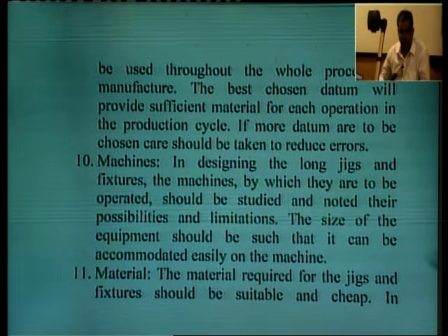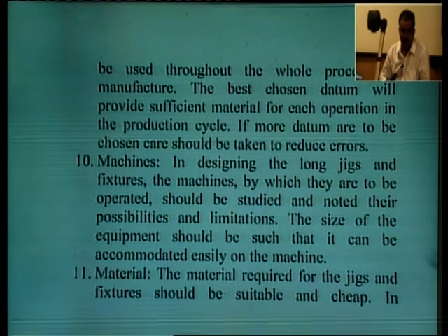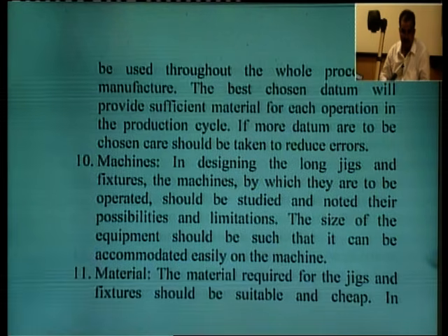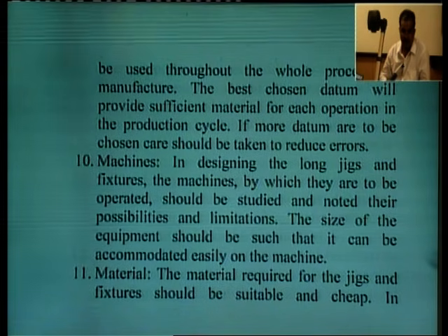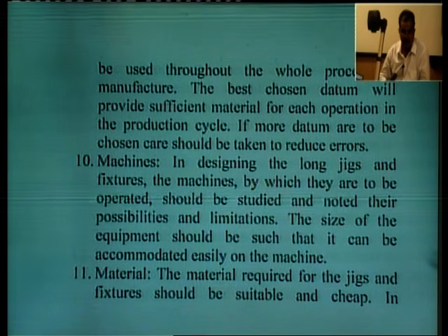So, while designing the jigs and fixtures, we must know the machine capabilities and limitations, because these jigs and fixtures are to be used on the machine table.